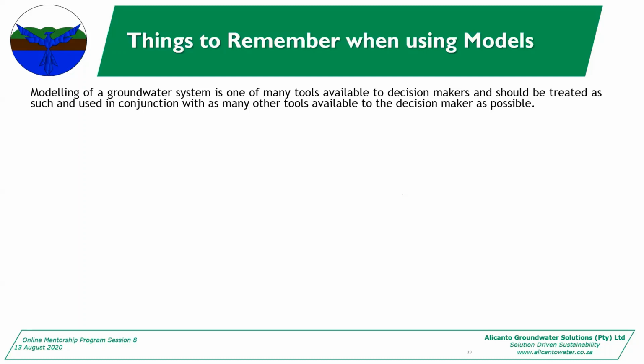And then important things to remember when you're using a model. Modeling of a groundwater system is just one of the tools available to decision makers, and you should treat it as such. This is not the silver bullet. This is not the be-all and end-all. You should use your model in conjunction with as many other tools as possible to make your decisions. Use it in conjunction with your geophysics, your drilling, your pump testing. Don't detach them from one another.